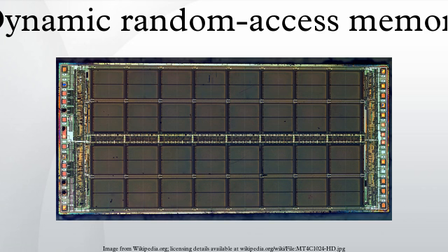1T DRAM. Unlike all of the other variants described in this section of this article, 1T DRAM is a different way of constructing the basic DRAM bit cell. 1T DRAM is a capacitorless bit cell design that stores data in the parasitic body capacitor that is an inherent part of silicon on insulator transistors. Considered a nuisance in logic design, this floating body effect can be used for data storage. Although refresh is still required, reads are non-destructive. The stored charge causes a detectable shift in the threshold voltage of the transistor.